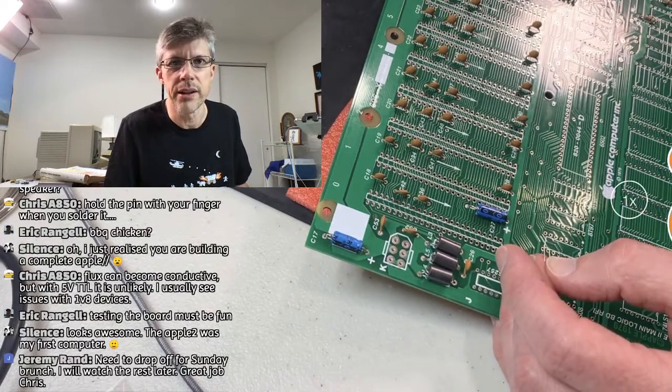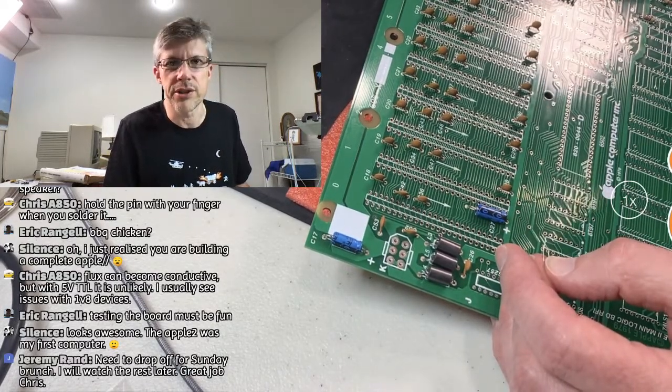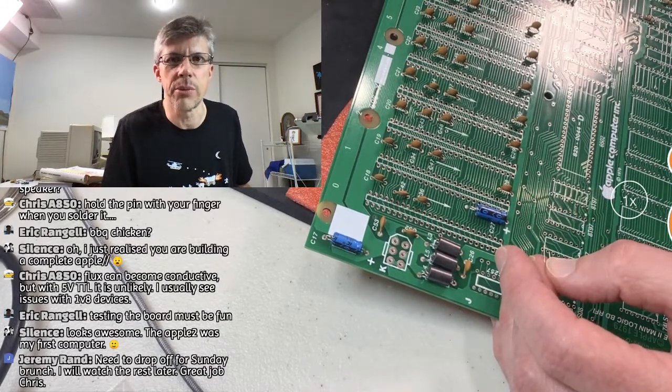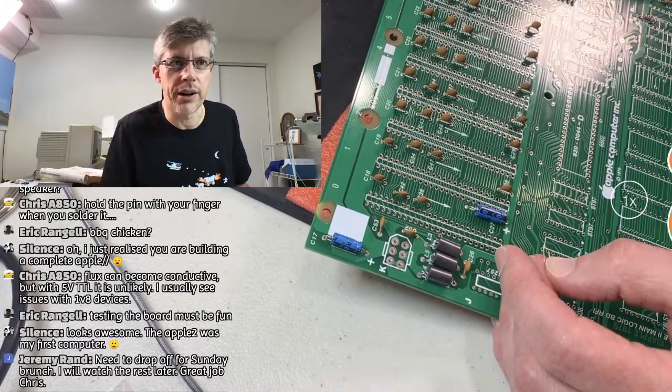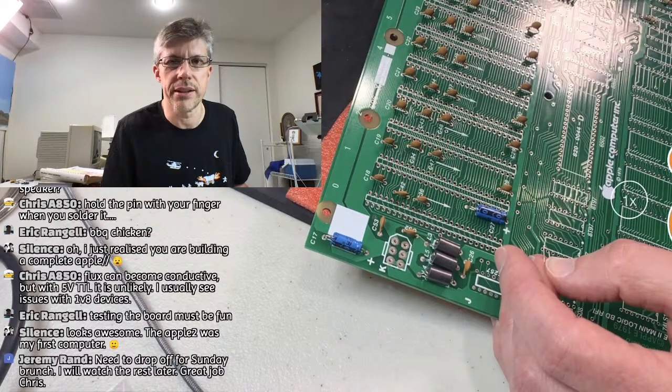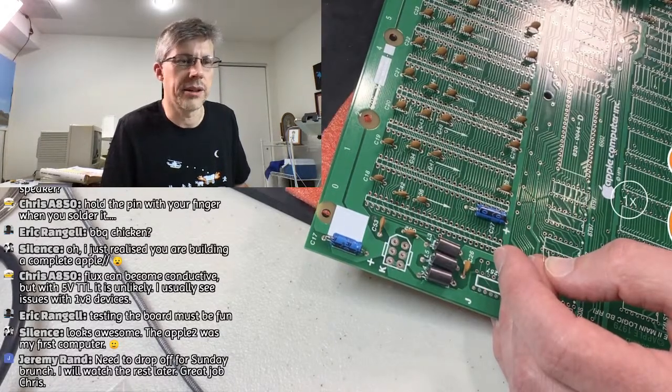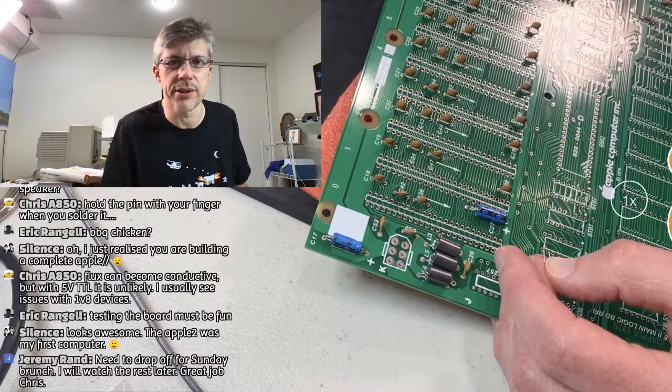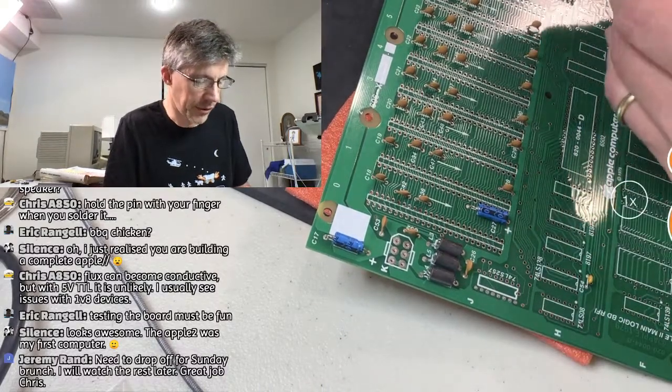And so at some point, especially once you get the chips in there, you'd have to switch to an oscilloscope and actually have power on it to see if there are any sort of problems, just because things are connected together with capacitors, which can goof up your readings.